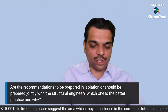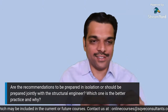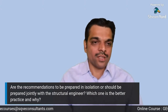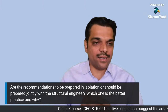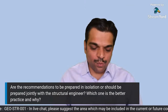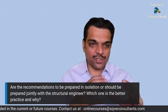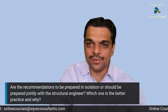See, there are two parts in the geotechnical investigation report. First is all kinds of testing, where we have defined the type of soil we have on the site, right? But the second part, which is the most important, is the recommendation part, so that needs to be done, I think, jointly by a structural engineer and a geotechnical engineer. As a process, it may happen that the geotechnical engineer puts up a draft recommendation, and then definitely those can be fine-tuned based on the interaction. But this is a very important point which we will address in the course.